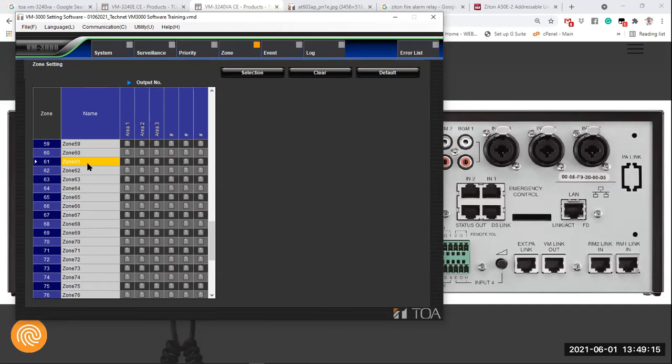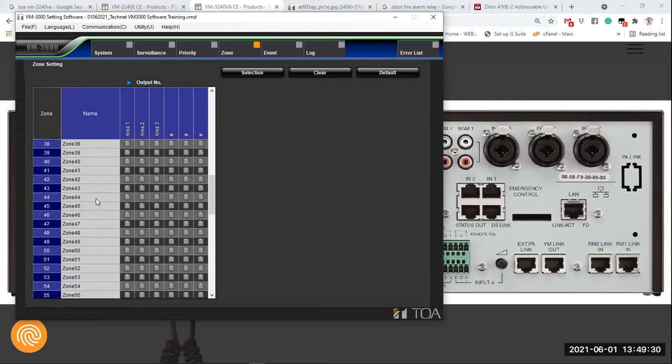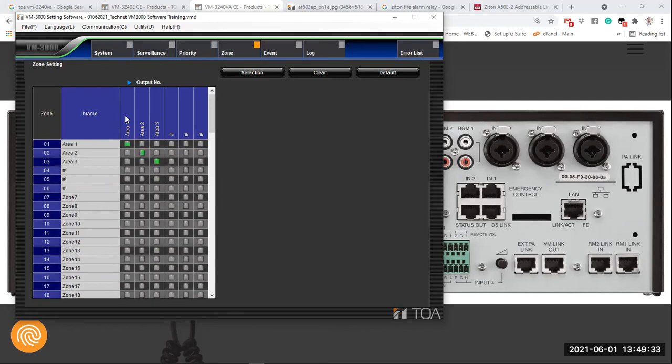The truth is, I am not wrong. It actually does 60 zones. However, you can do zone 61 to zone 89 as a combinational zone. Let me explain what this means. By default, Emma, you have here 3 zones that are going to be active. I can come here and create a virtual zone called, let's say, A1 plus 2, meaning I'm going to create a special zone where A1 is always linked to A2.